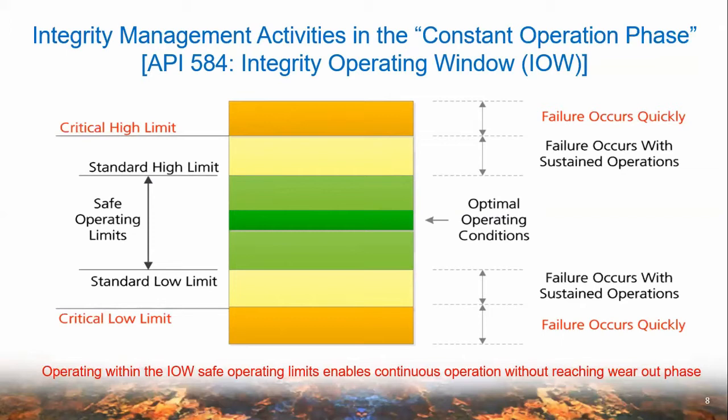I am aware of a situation in which a particular pipeline was protected with an external coating that was rated to 40 degrees centigrade. And during operation, the temperature exceeded 80 degrees centigrade just for 4 hours. And that completely destroyed the coating. The company had to recoat the whole pipeline section. So it is very, very important to understand the variations in the operating conditions.